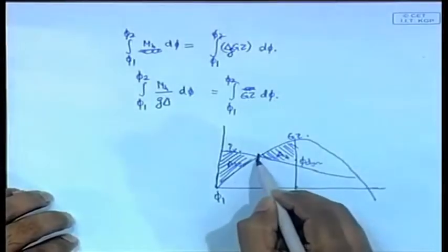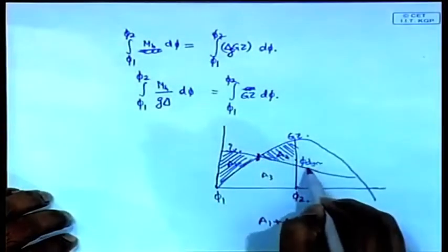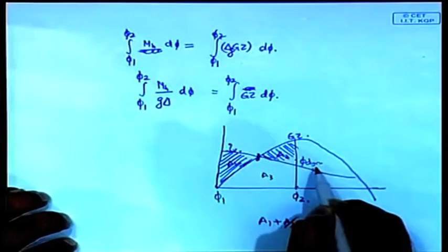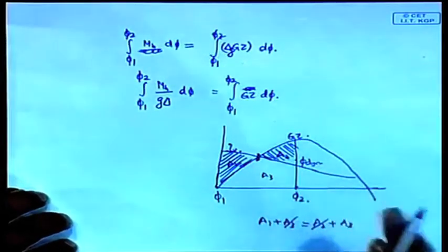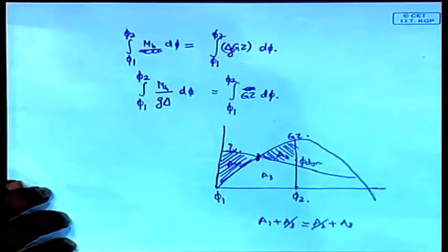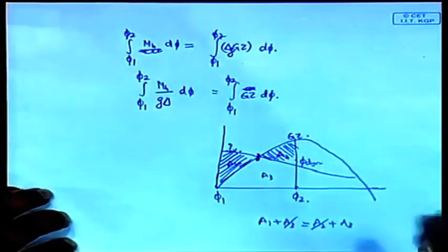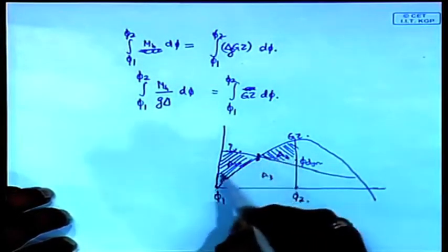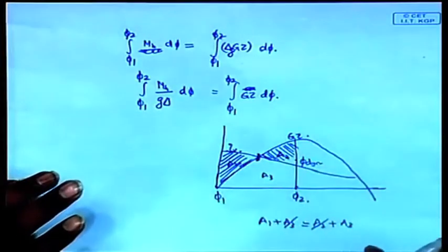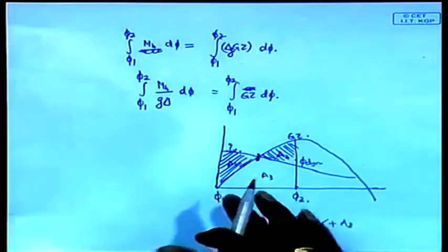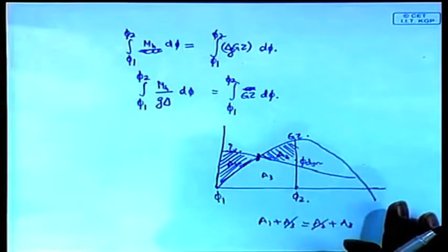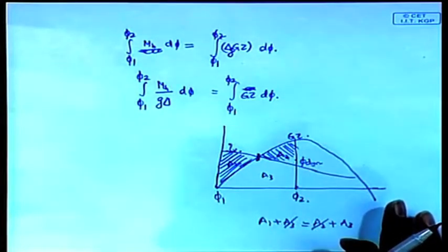the wind heeling moment, but energy is there causing it to heel further, and till that excess energy dissipates, it will continue to heel. Therefore, though this is some kind of equilibrium, it will continue to heel till it reaches phi dynamic. So we can say that phi dynamic is a possible state when it will definitely stop. After that the ship will not heel further, and therefore this is the concept of dynamic stability.